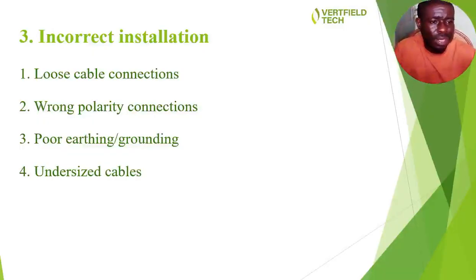Undersized cables, yes. Not just undersized cables, undersized and oversized cables. When your cables are undersized, that means you're using a too-thin cable. When you're using a too-thin cable, there will be resistance in that your cable, and when there is resistance, there will be heat. There will be heat generated, and when there is heat generated, there will be energy lost through that heat generation.